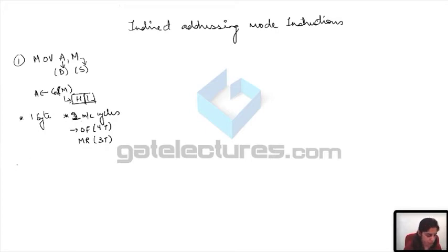Next instruction that we see here is arithmetic operation. ADD M is similar to ADI data. There we are giving the data itself. The data is going to be located in the next memory location. Here you are going to get the data from memory. How? You extract the address from HL pair, and at that memory location, whatever data is stored, you are going to add it to A. So A is going to be added with contents of memory, address of which is pointed by HL pair. So this is also going to be a 1 byte long instruction.